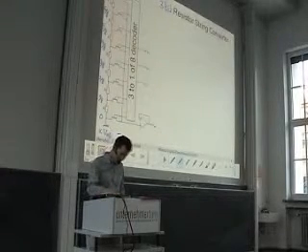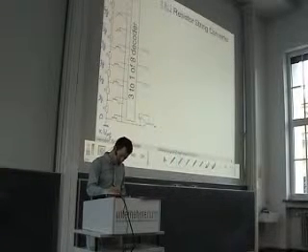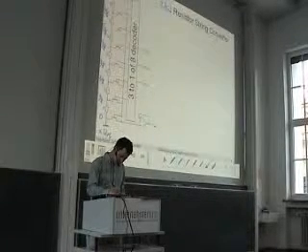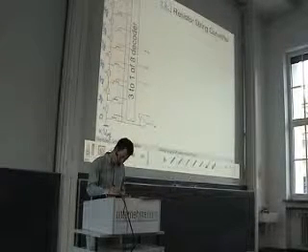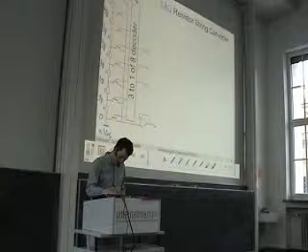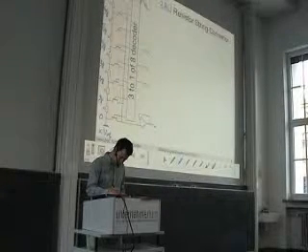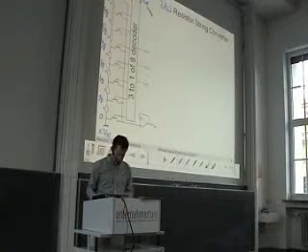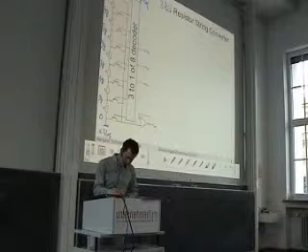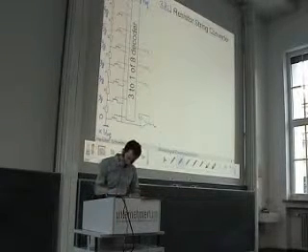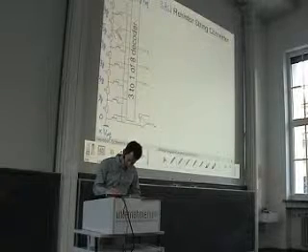So we have a VLSB equal to Vref over 2 to the power of n, which is in our case 1 over 8 times Vref. By doing this, we have generated all voltages at these nodes.